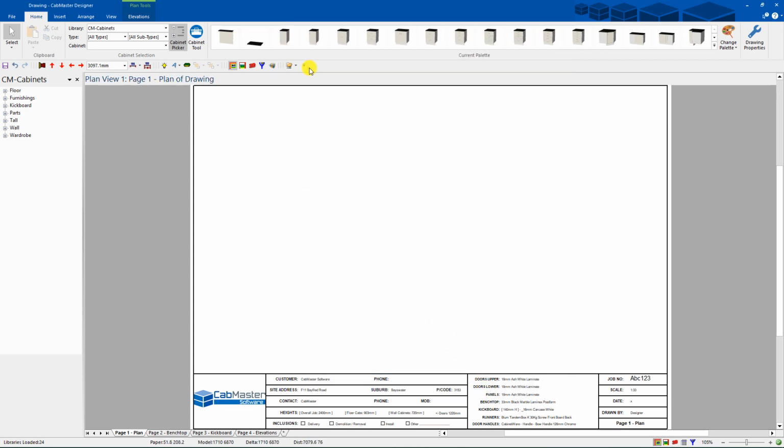Now, I like to set up my own toolbar down here. This is completely configurable. This little toolbar normally sits at the top above the file here. There's this little arrow down. If you choose that and go show, it'll say show below ribbon, so it moves it down to where it is now, and you can click more commands and you can add in whatever buttons you like. So you can choose your favorites. I'm not going to use it today because I'm going to use the standard buttons that everyone else has.